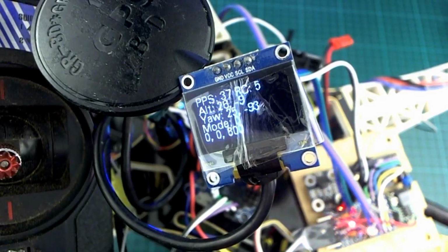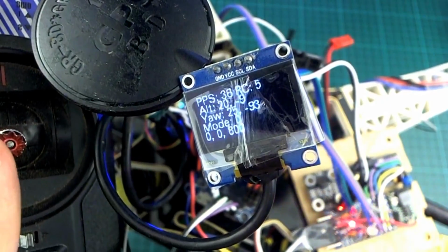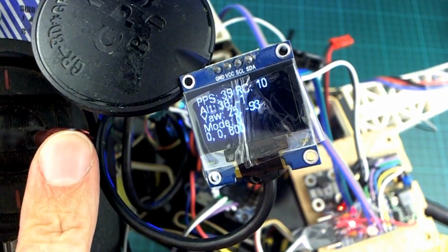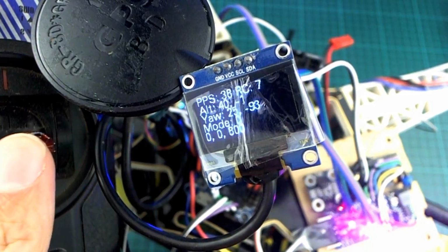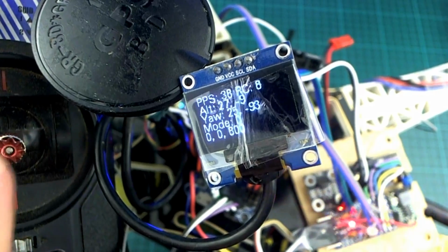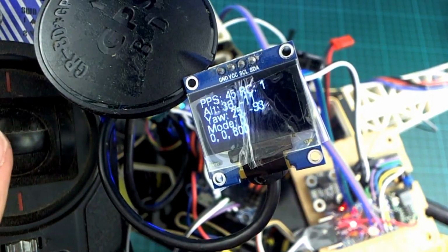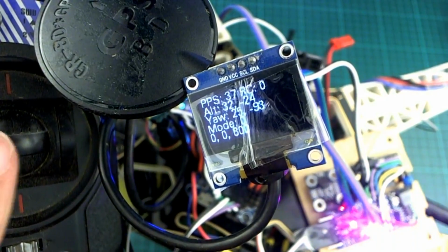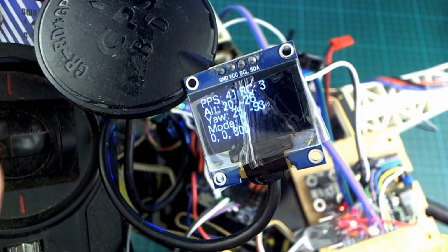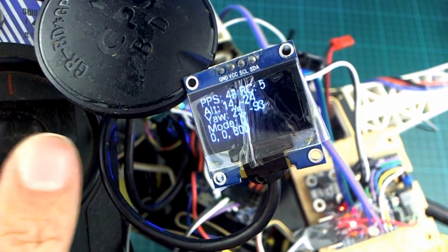Alright. So you see the number RC5 in the top right. This lets you check, if I move my roll stick to the right, it should go to 10. It's a little bit slow to react. But when it's in the middle, it should be 5. And if I take it all the way to the left, it should be 0. So this is just to let you see that information is being pulled from the CleanFlight controller successfully.